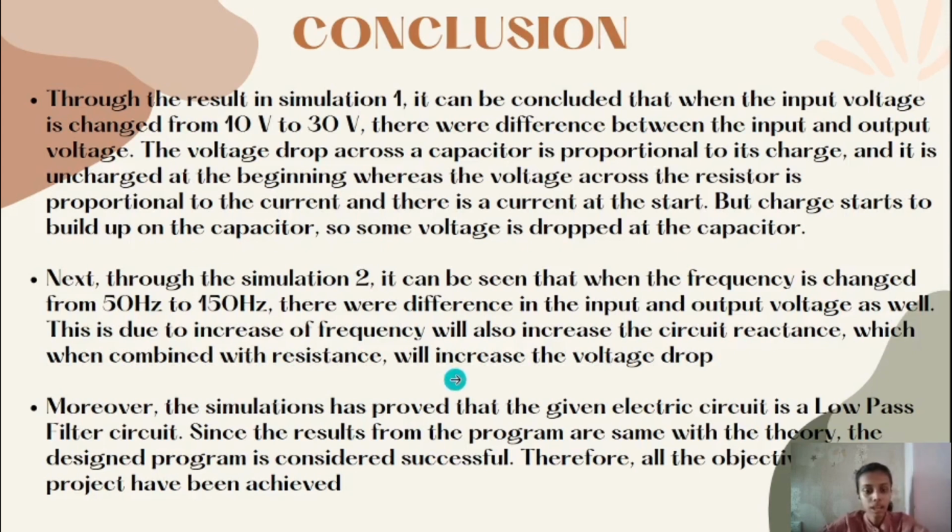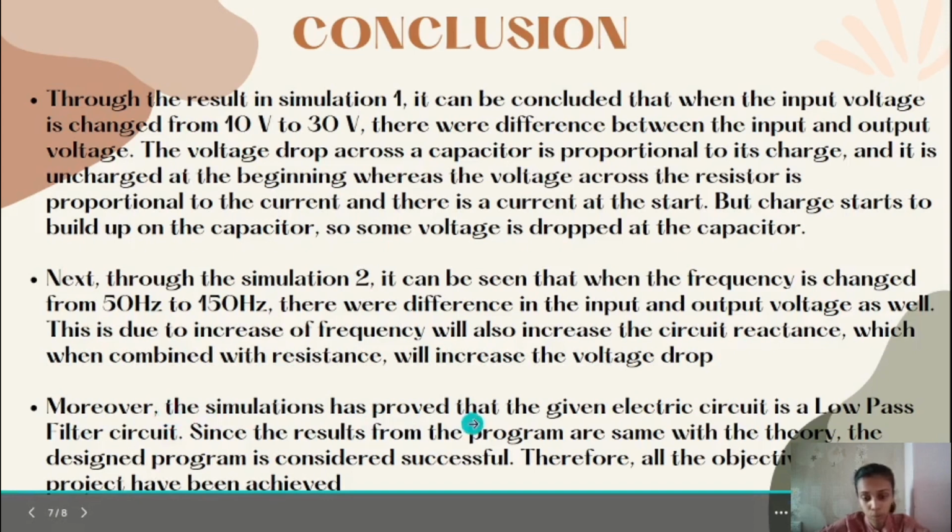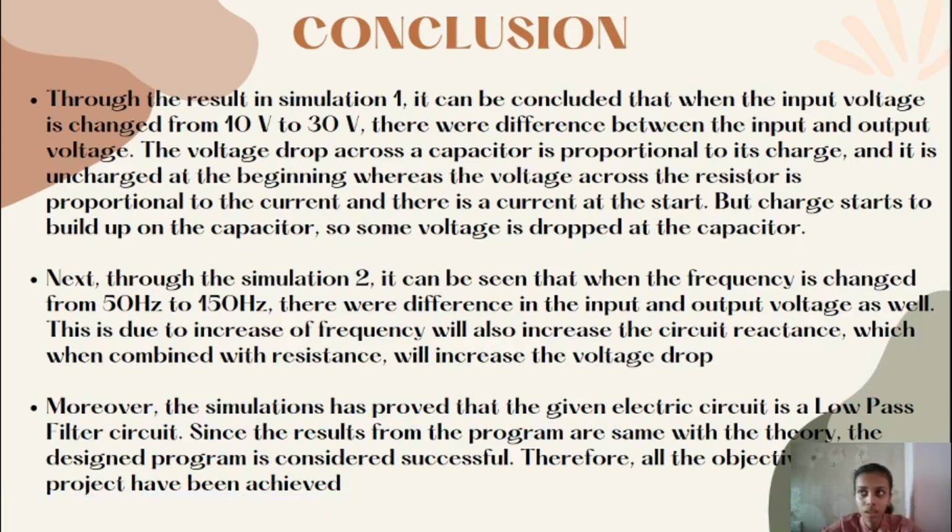And last but not least, moreover, the simulation has proved that the given electric circuit is a low-pass filter circuit. Low-pass filter means that it will block the high-frequency signal and it will only allow low-frequency signal.